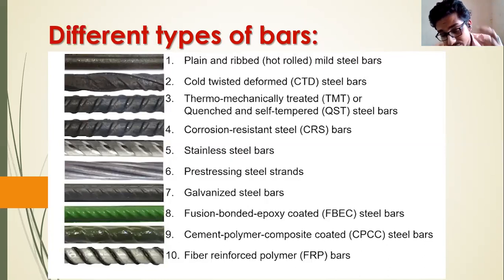When the wires start to corrode, the corrosion products first accumulate in the spaces between the strands. Once these spaces are filled, only then will it come up to the concrete surface. So the alarm of corrosion in prestressing strands is quite dangerous, because you may get the alarm only after a huge devastating effect.